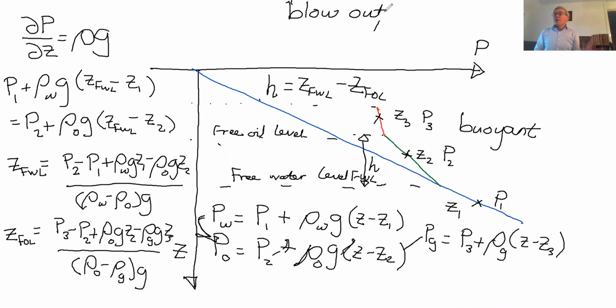So if I were to just drill a well and allow water to be in the well, and I'm drilling and the water's circulating and getting rid of the cuttings, when I encounter a hydrocarbon, that hydrocarbon is at a higher pressure, it will move very rapidly into the wellbore, and there will be a sudden release. And of course, once it's in the wellbore, then what's in the well is less dense, and so there's an even bigger pressure difference, and it just escapes outwards. And that, as I said, is extremely dangerous. You want to avoid a blowout.